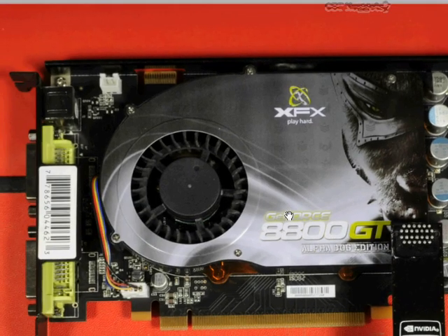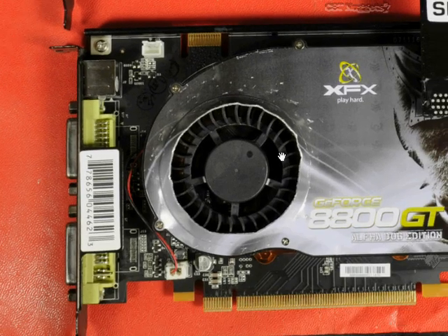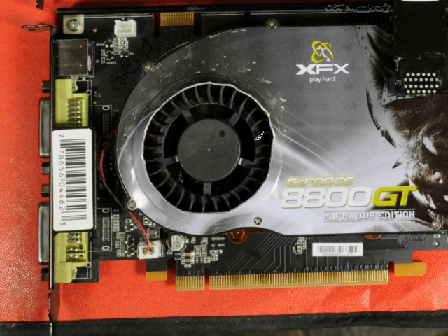I just want to share this real quick. And this might be useful in your own troubleshooting as well, by the way. I had ganged these two together in an SLI connection, and I didn't seem to be getting the video performance that I expected to get out of these connection combinations. And I looked at this video card, and it was working just fine. The fan was spinning just fine and everything. And I had to cover off the computer so that I could observe this. And then I looked at this video card, and this fan here was seized up. It was not moving at all.